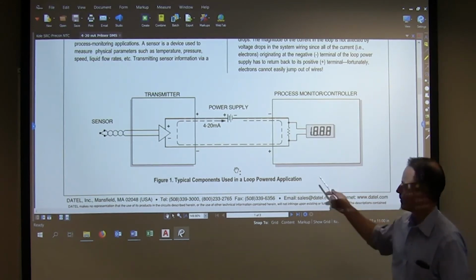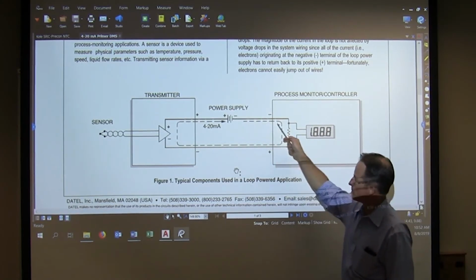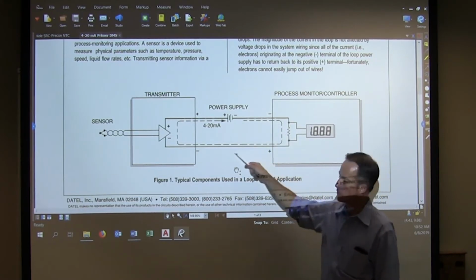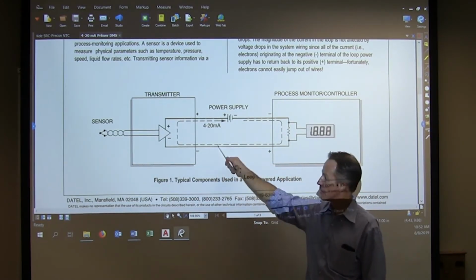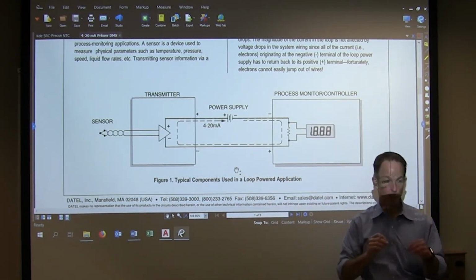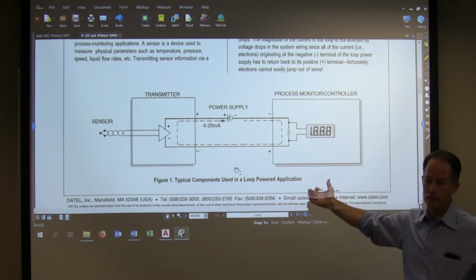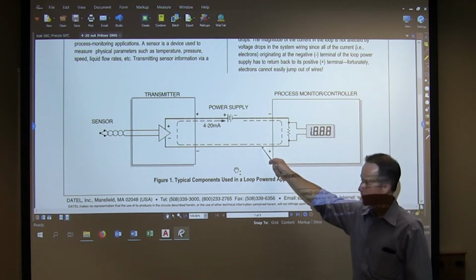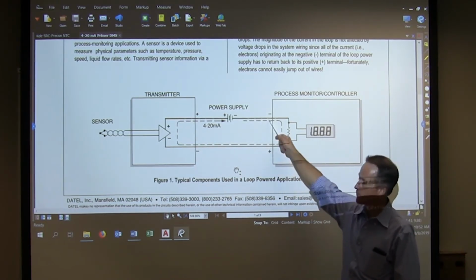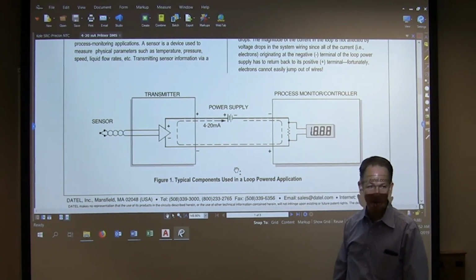So this needs to have at least some capacity to also have voltage, because that wire is like a big resistor, right? It's just a really tiny resistor stretched out over a long distance. So I may have maybe a 1 volt drop on each one of those legs of that wire.